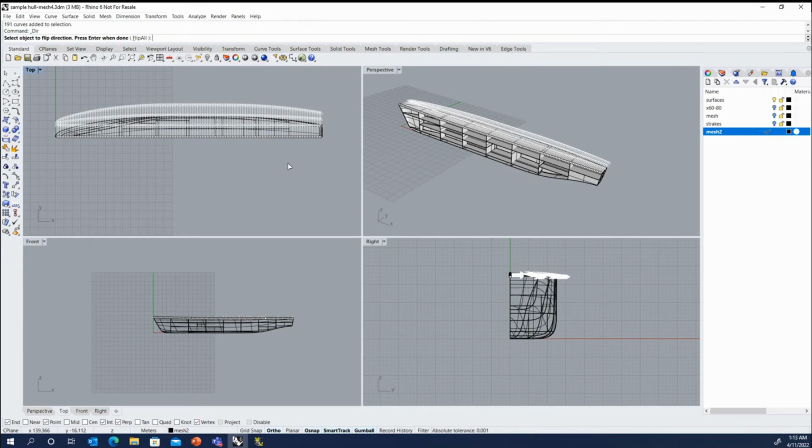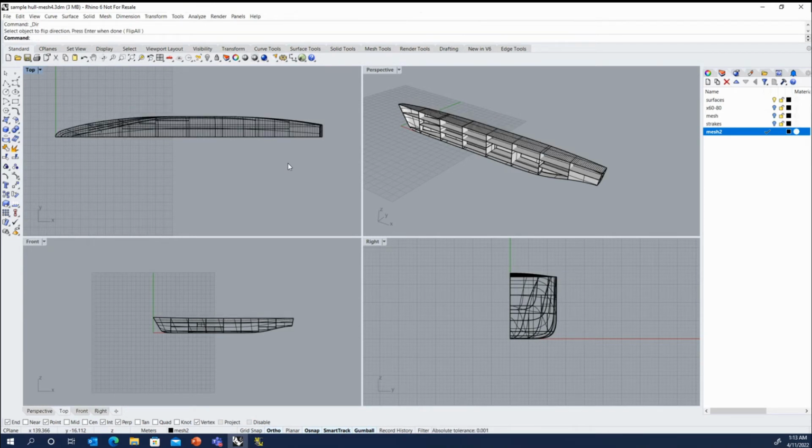And when you do a group select, such as dragging a window or typing a command like select curves, the order that it's going to use is the order in which those curves were created. So right now, because they were created from the contour command, they were created in order from 0, 0, marching down the x-axis in 1 meter increments. So they were created in this order. And since I haven't edited any of them, they're still in that order when I do a group select.